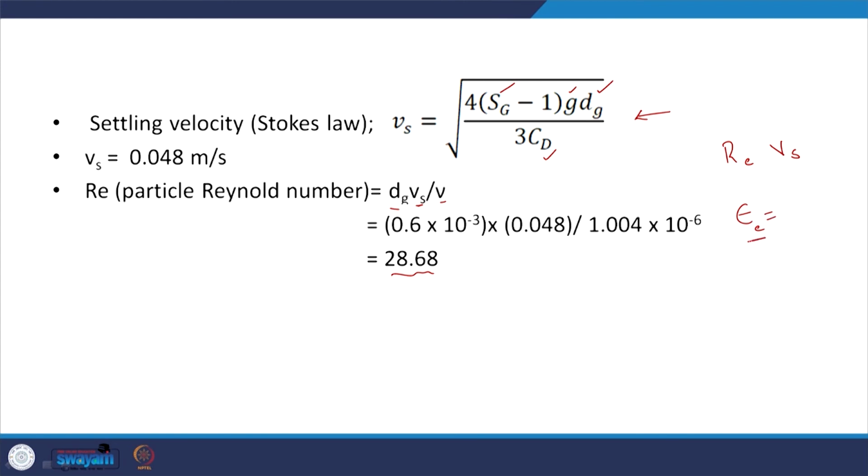equation, or now we have to calculate the porosity of the expanded bed before we can put that into this equation or a similar equation to be able to calculate the backwash velocity. Let us see how we can calculate that porosity of the expanded bed. That we will look at by looking at the media, right.